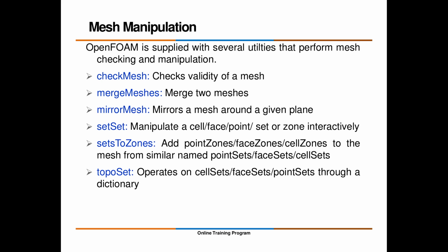Plus, believe me, if you are working with turbulent flow and you created a boundary layer mesh, OpenFOAM is going to give you the aspect ratio error, but no worry about that part, because it is a boundary layer mesh. You can modify that mesh by increasing the element size in the stream-wise direction, because in the cross stream-wise direction we have the boundary layer. Wherever we have a boundary layer we have very thin layers, otherwise we cannot capture the proper boundary layer. So for that OpenFOAM is going to give you the warning or the error, but no worry, you can work with that. But if OpenFOAM gives you the error about skewness, please don't work with that mesh. You have to change the mesh.